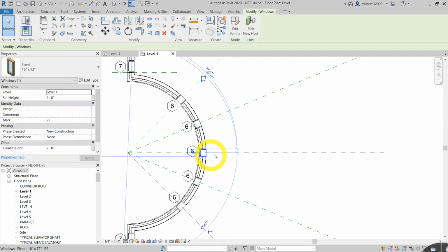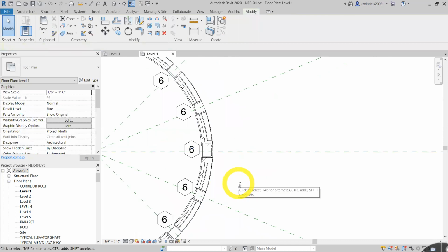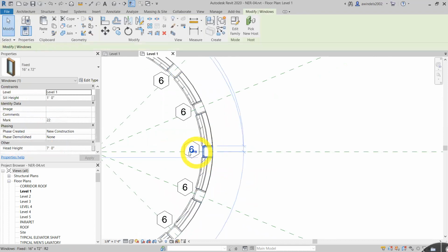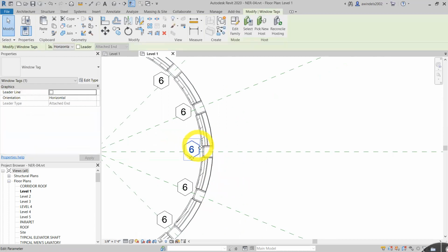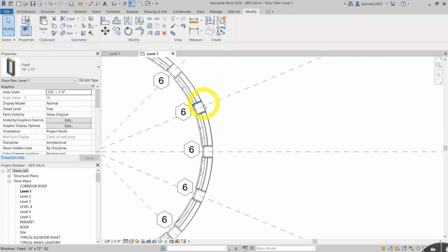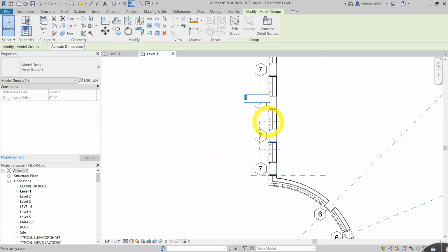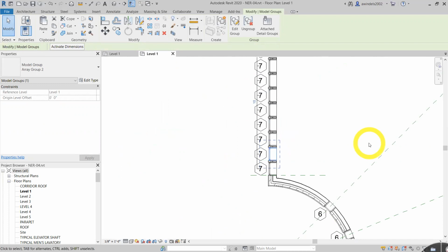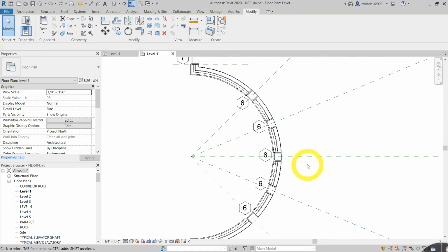Now when we select those, see, when I flip that, I get a different type of join. Interesting. That window, we don't have the group and associate. So I can't add more in this array after the fact like I can with this one right here. I have to go back and redo the command essentially. So I added 10 on the fly. This one I cannot. So that's kind of critical to know.